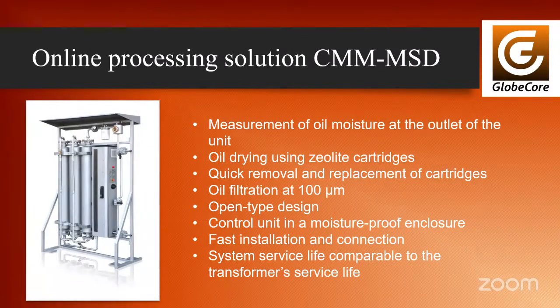Online Oil Drying Station CMM MSD. The CMM MSD unit is made to remove water from a transformer all the time. It keeps the transformer dry, no matter the oil temperature or water content. The unit has an open frame design. The pump and control system are in a sealed cabinet protected from moisture, IP54.